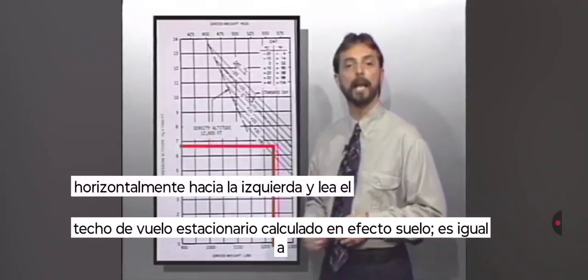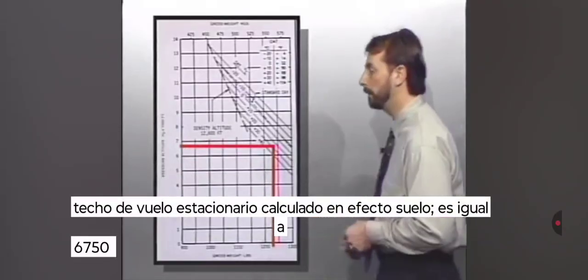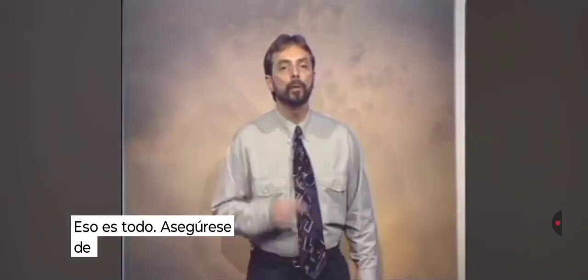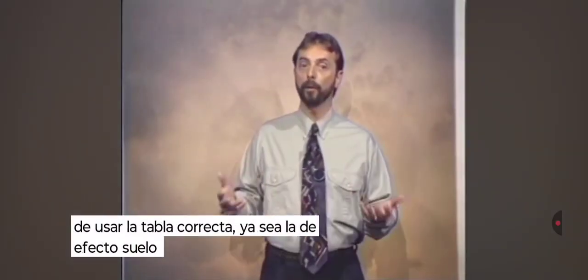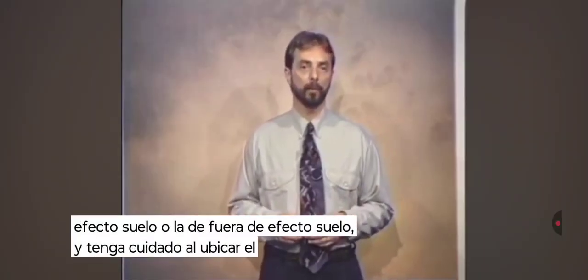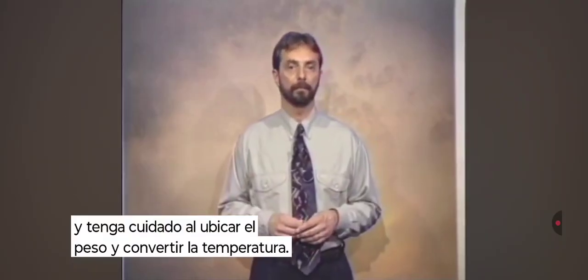It's equal to 6,750 feet. That's all there is to it. Just be sure to use the correct chart, either the in-ground effect or out-of-ground effect charts, and be careful when locating the weight and converting the temperature.